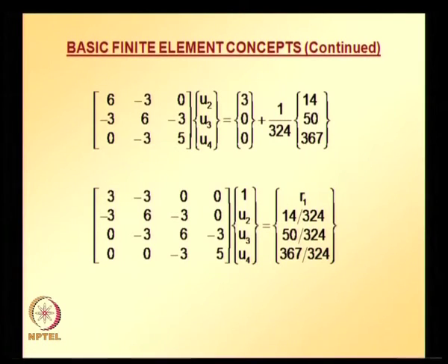using this idea, global equations obtained using variational method are identical to those obtained using Galerkin method, which you will see in a while. So, whatever procedure we are following here, variational procedure, you have seen from the examples that you looked at for classical approximate techniques, the exactly same solution you get if you adopt variational method or Galerkin method. So, similarly here you get exactly the same equation system if you use the second approach, that is, wherever the essential boundary condition is known, at that location in the force vector you make that component unknown.